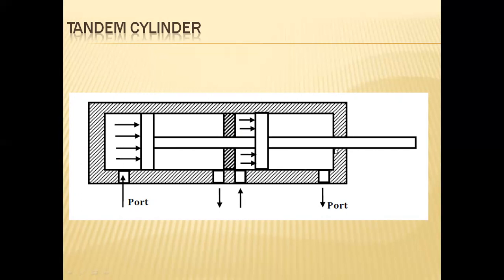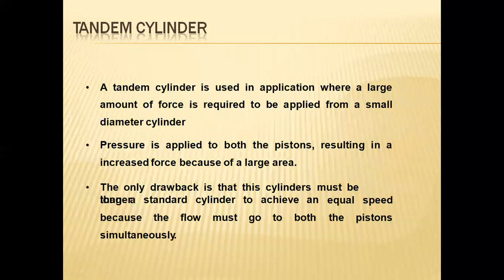Vice versa, if the return stroke needs to be commenced under loading conditions, then port 3, port 4 and port 2 have to be pressurized with fluid. That is the tandem cylinder.